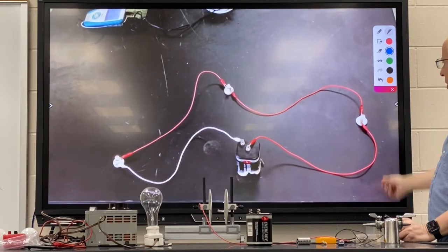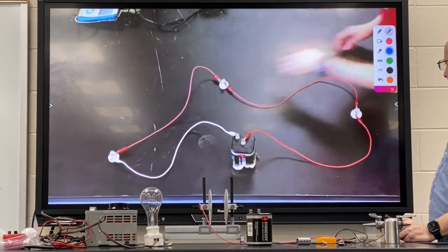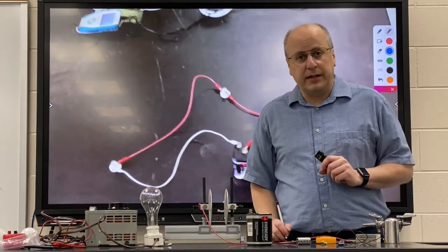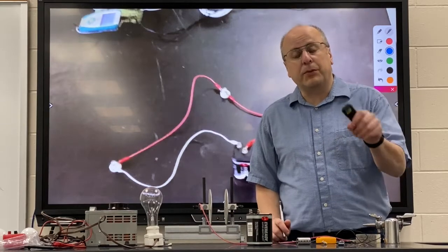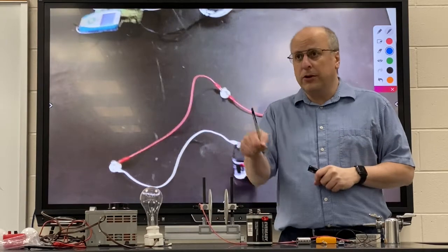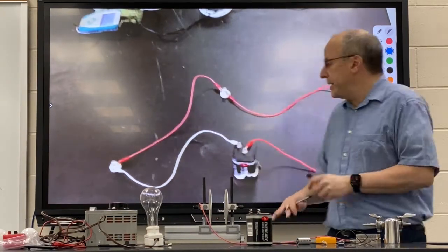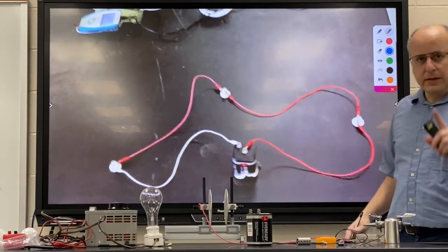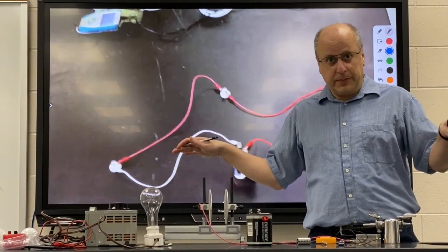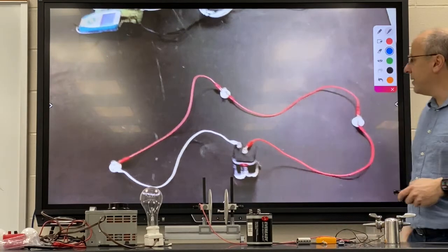Now you'll notice all three bulbs are on, but if I unscrew one bulb, all three of them shut off. A series circuit has one path, so if I break that path by a switch, by a fuse, by a circuit breaker, or by removing one of the lights, having one of the lights break, they all go off. Series circuit, a break anywhere shuts down the entire path, shuts down all the objects on that path.